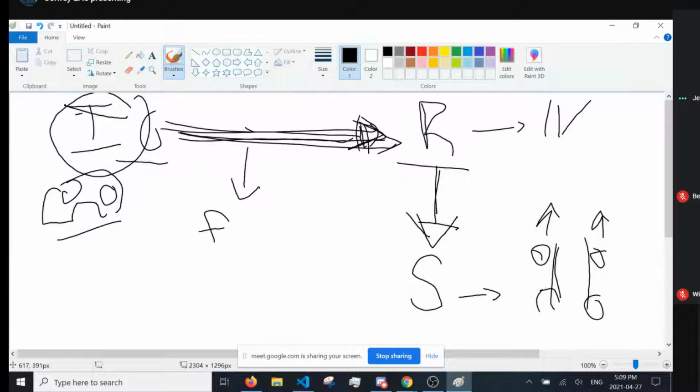Right? But with this system, the only things that we're able to control are, we're not able to abstract in any sense. And I'll show you what that means, right? Essentially, that means that our inputs are only allowed to take a form that our robot inputs allow. So in this case, we can't actually directly control the speed of any of our wheels, even if that's what we would like to control. The only thing that we can actually control is the voltages on the motors themselves.